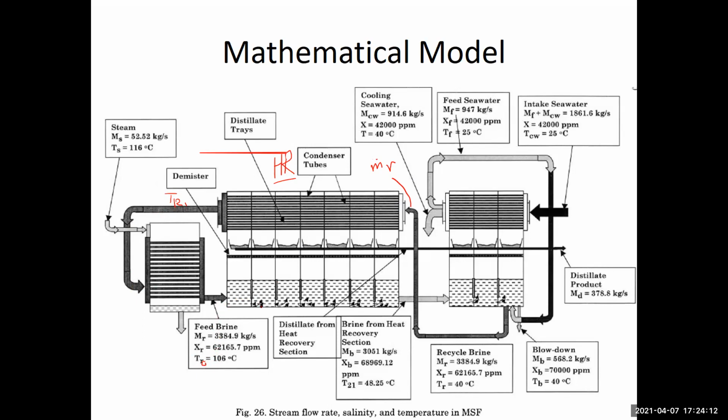After that, flashing is going to start, and it will decrease in a value of delta T for every stage. We assume this delta T is constant, and similarly, upon the assumptions of neglecting the boiling point elevation effect and assuming that the vapor temperature is equal to the effect temperature, we could come up with the equality of delta T in this section, upper part, and delta T right here. So again, that was basically the same as we did for the once-through system.